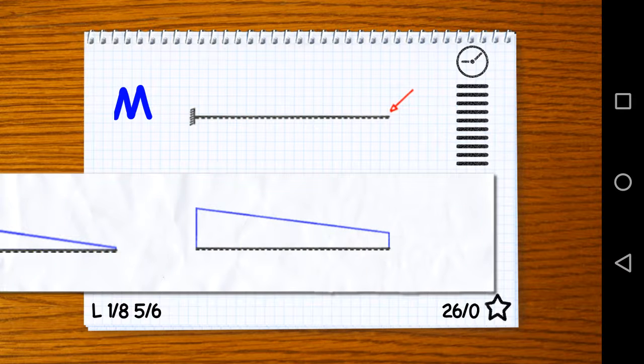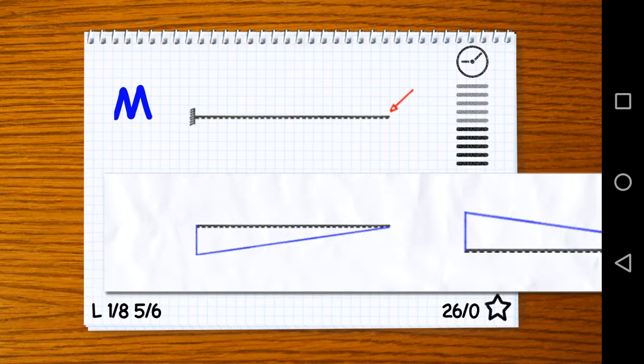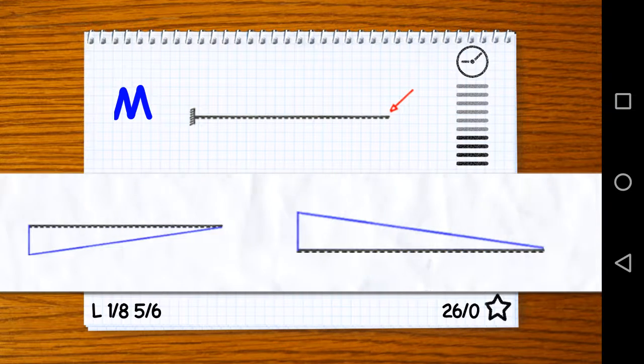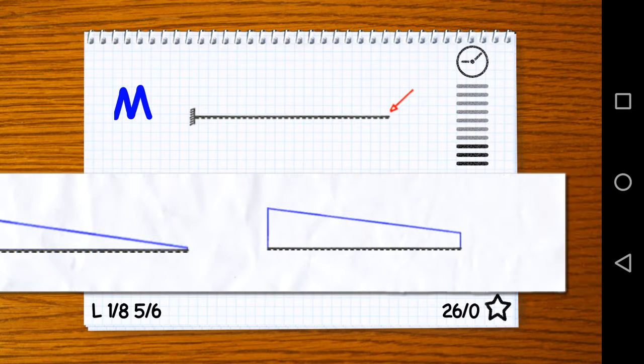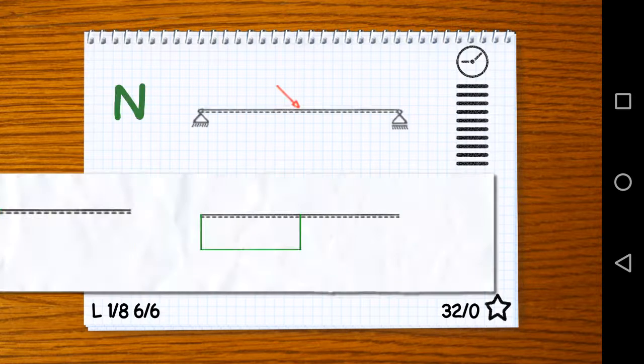Here, bending moment. What's going to happen? It's very similar to a case we had before. The right end of the cantilever beam here is going to be bent downwards, so we're going to have a deflection downwards, meaning that the curvature will be open downwards. That's a positive curvature, meaning a negative moment. So with two negative moments, it can't be the left answer here, it can only be the middle one or the right one. Now the force is at the end of the cantilever beam, so the moment there should be 0. We don't have any single moment there, so yes, the answer in the middle.